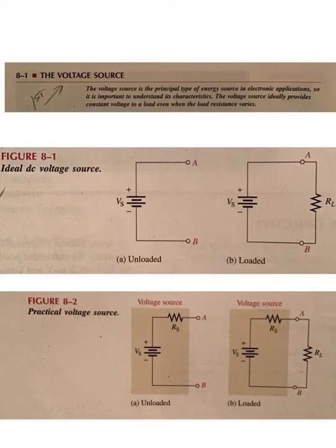Is it like an ohm meter? Is it like 10 to 20 mega ohms? Is it like that? Or is it different? What we're going to find out is that a voltage source's job is to provide constant voltage to something that's plugged in. No matter what is plugged in, we want to keep that voltage constant, even though the things we plug in can change, and that becomes very important. If you remember with an ohm meter, we got away with hooking it in parallel all over the circuit because its impedance was 10 to 20 mega ohms.